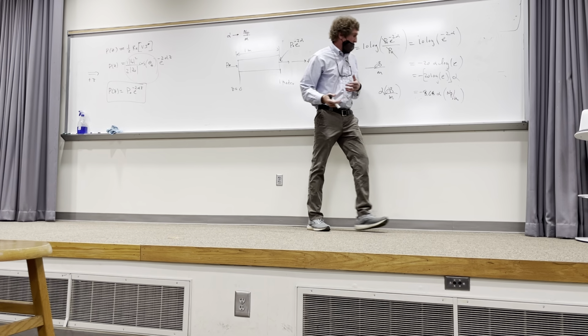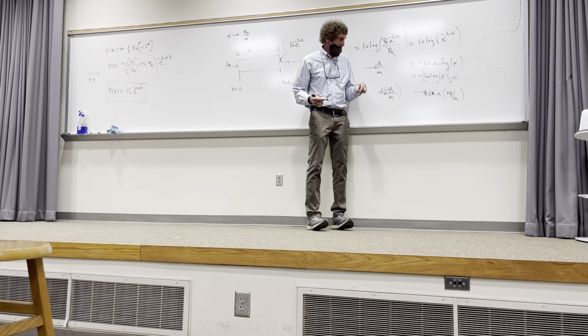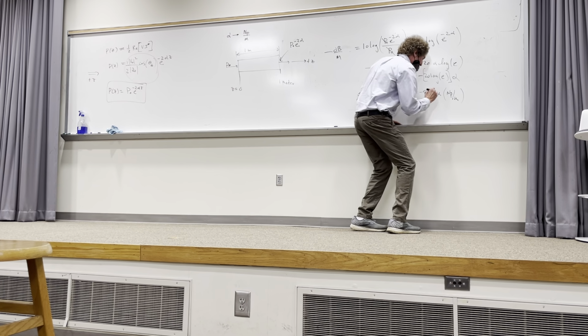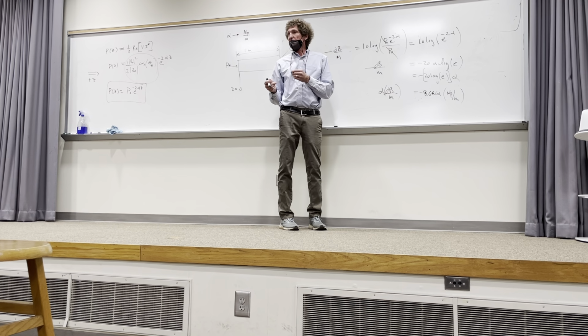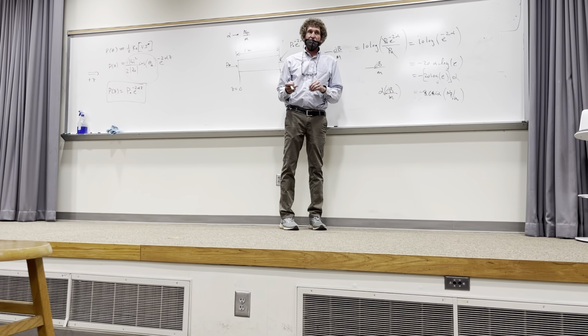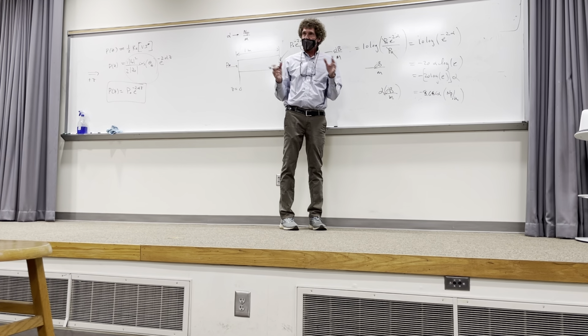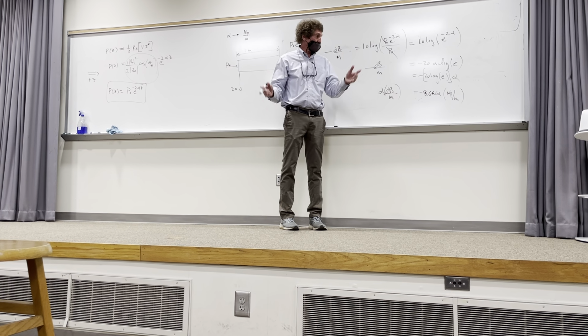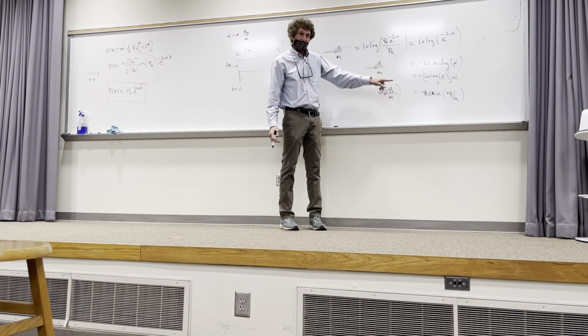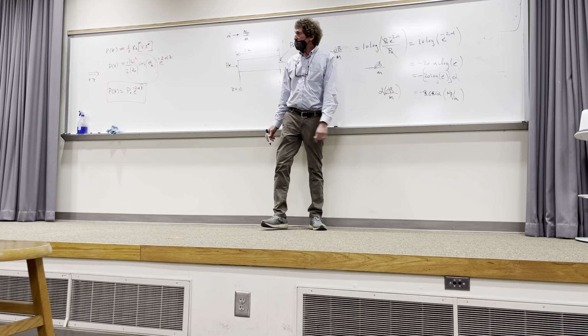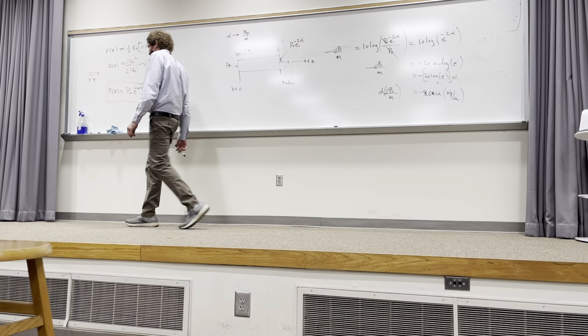If I multiply that by 8.686, then I get the attenuation in dB per meter. That's the relationship, and sometimes people get a little angst about that. But remember, if attenuation is given in dB per meter, that's this side. If you want alpha, you have to divide this quantity by 8.686. Follow me, class?